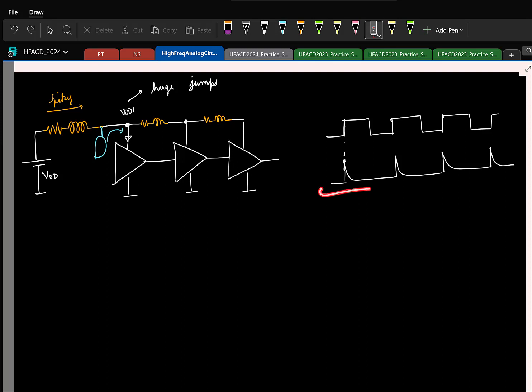And if I look at the frequency spectrum of this current, do you think it will have a significant high frequency component or low frequency component? It's very high frequency. So this path here should provide a very low impedance at high frequencies compared to this branch. Only then the spiky currents will prefer this path. But at DC, what can you say about the current that should flow here? That should be 0, because at DC at least you want this guy to be short like this, right? So essentially you want to put something that is providing a very low impedance at high frequencies, very high impedance at low frequencies. What is it? Capacitor.